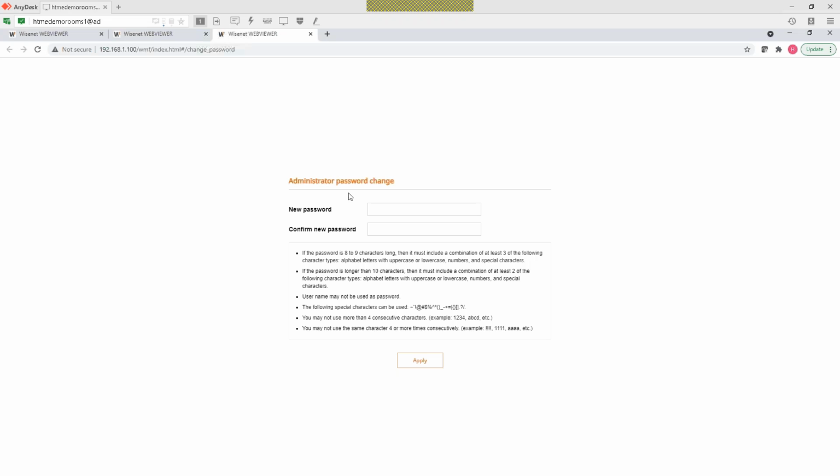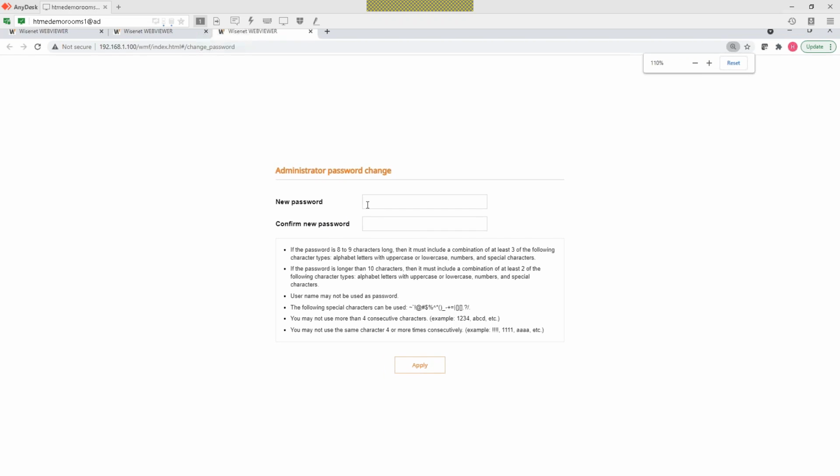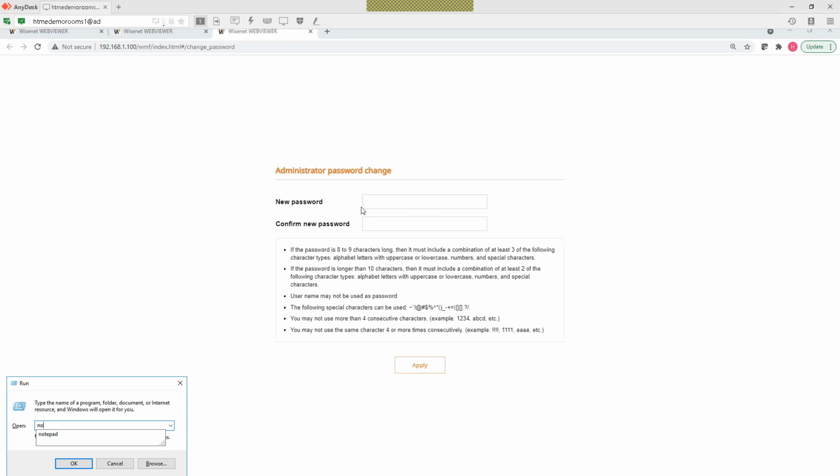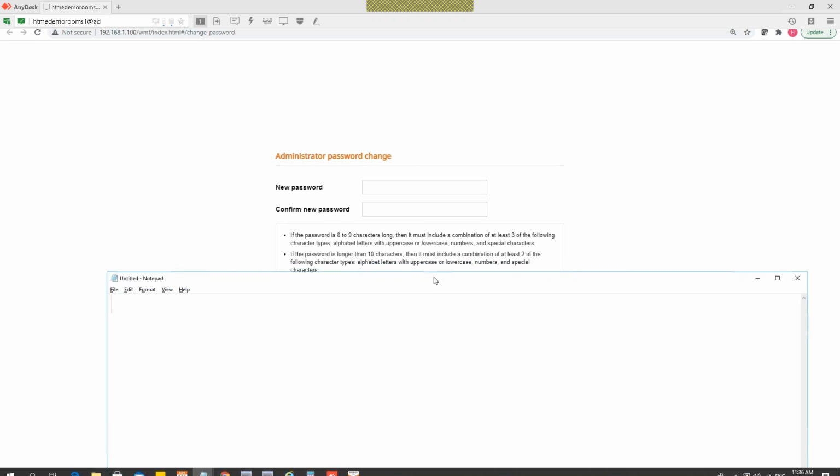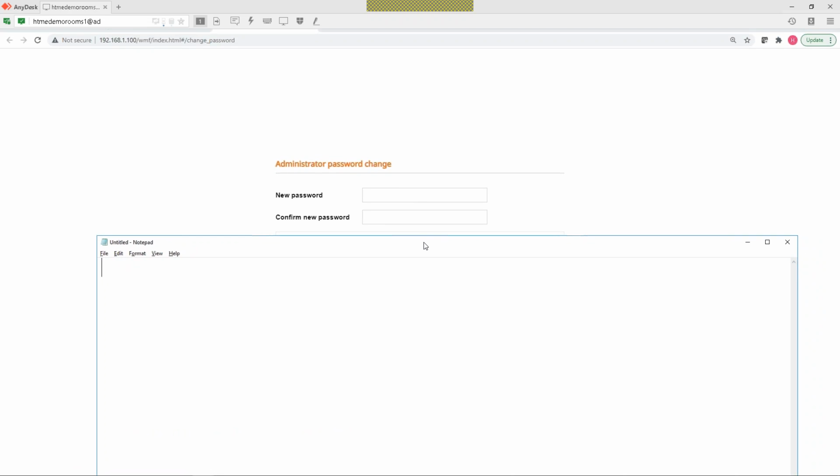You have to create a password for this camera. So when you log in, it will ask you to create a new password. It does not exist, right? So you have to create it. So for our training, I'm going to create a password, but I'm going to make it the same across all the cameras so I remember, and so if you want to log in and practice, you can also know the password. So I'm keeping a lab password for all my lab cameras. I'm using this capital ADMIN@12.